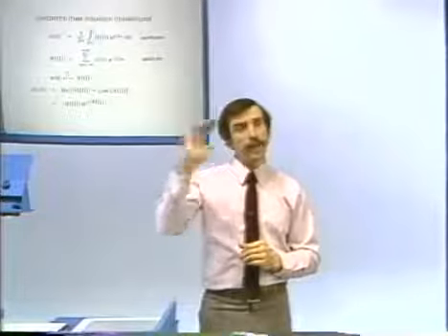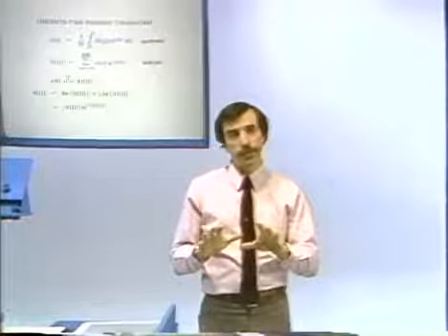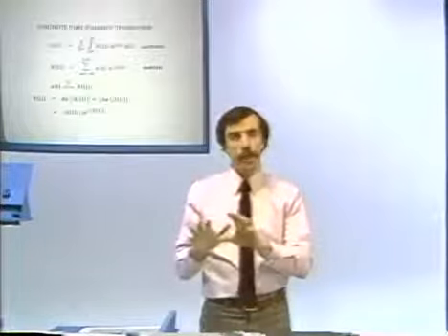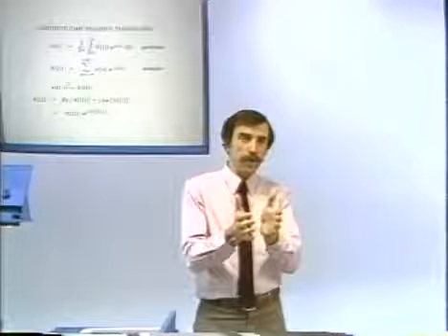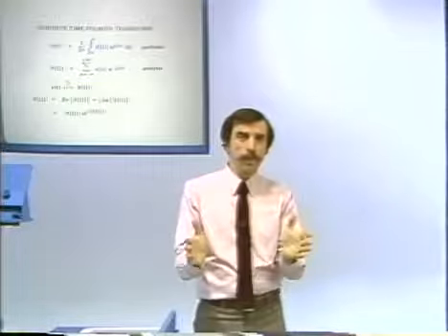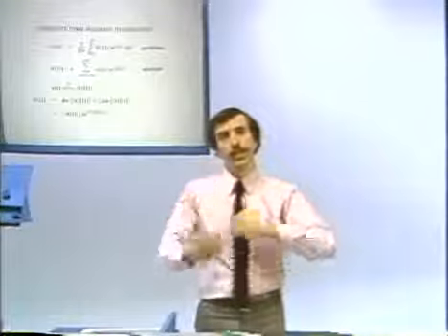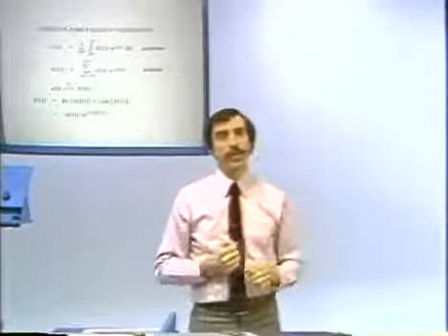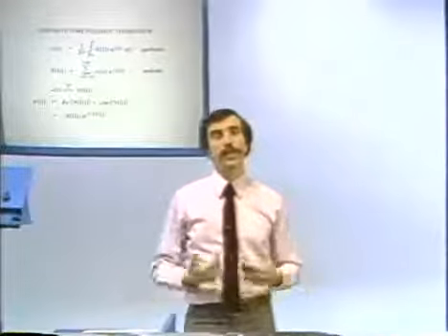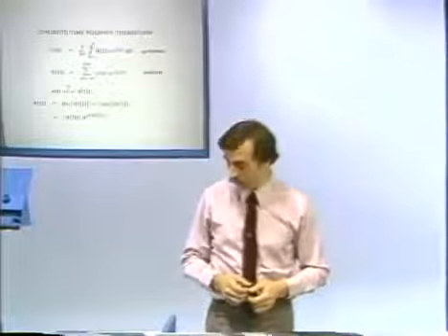It all stems back to the fact that when we talk about complex exponentials, and recall back to the early lectures, in discrete time, as the frequency variable covers a range of 2 pi, when you proceed past that range, you simply see the same complex exponentials over and over again. And so obviously anything that we do with them would have to be periodic in that frequency variable.